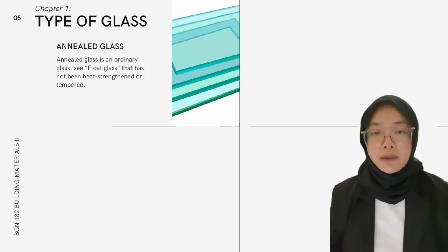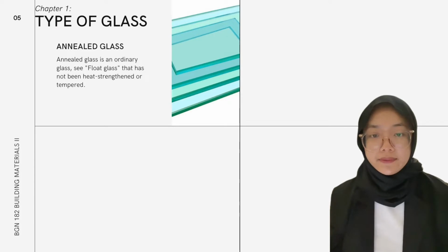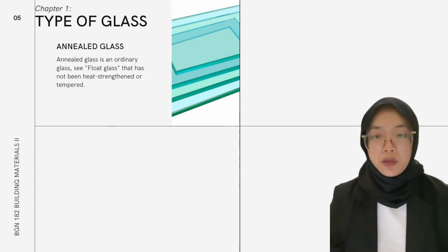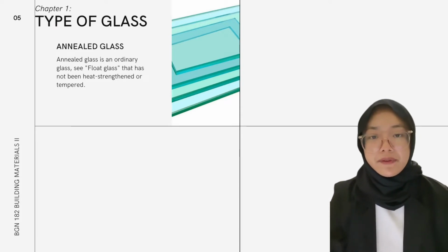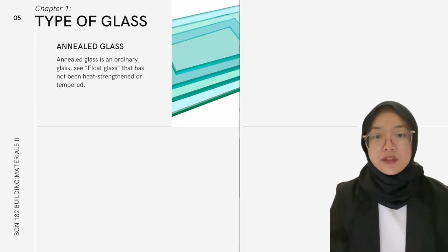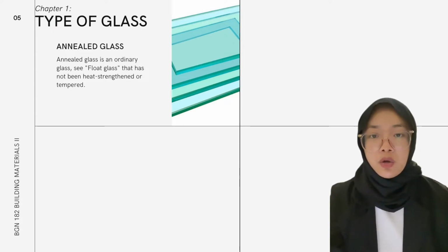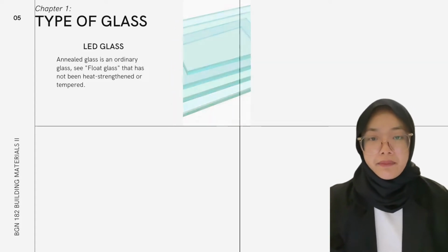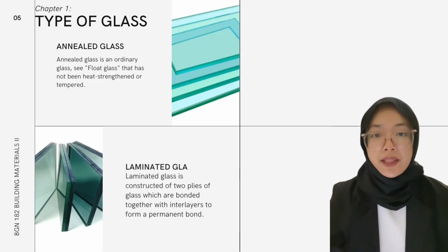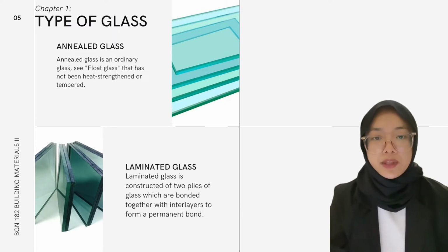There are a few types of glass that Sengli Sdn Bhd produced for the company. Firstly, we got an anneal glass, also known as clear float glass. Basically, this glass is distortion-free, precision flat, and transparent glass. In order to make an anneal glass, we must float a ribbon of molten glass over a bath of molten metal. Next, laminated glass. Laminated glass is usually used for windshield.